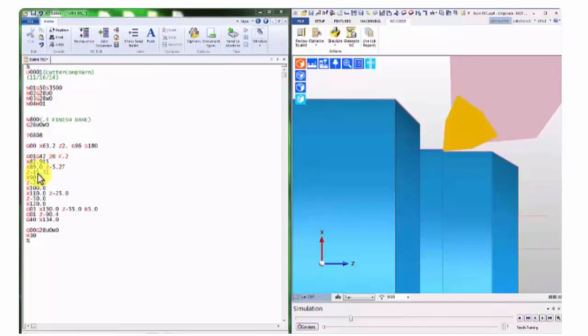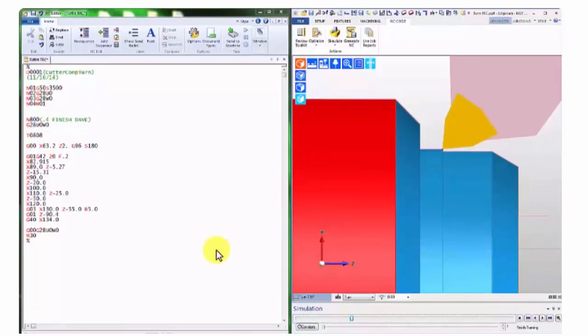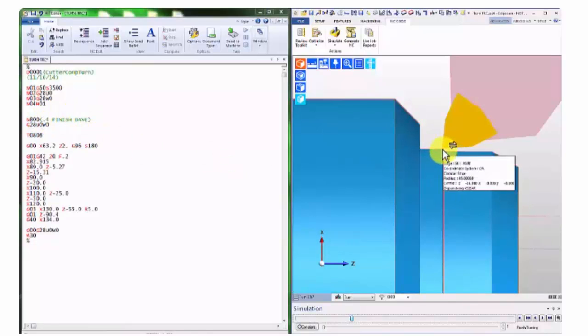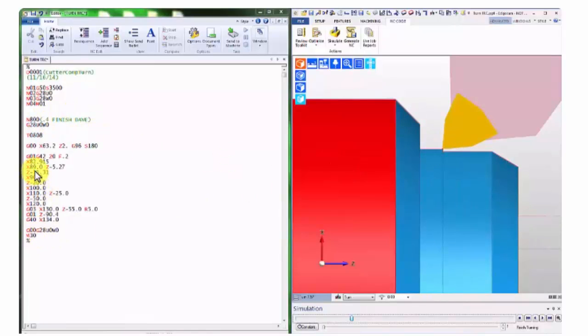So the control's just going to try and do this, but it's in tool nose radius compensation. Fortunately, our rad is only 0.4, so it's going to make just a tiny 0.1 move really up there, and it'll end up at the right place. So that's going to work, but it's not going to work if that tip rad is bigger than 0.4, and that is one of your most common errors that you're going to get. And really effectively you're just asking it to do something rather stupid.